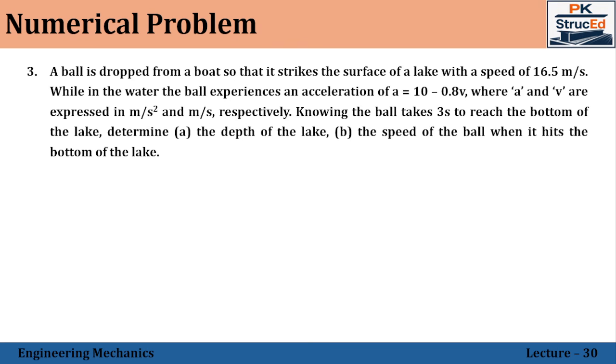First of all, you can see the relationship is given for acceleration in terms of velocity. A ball is dropped from the boat so that it strikes the surface of the lake with a speed of 16.5 meter per second. While in water, the ball experiences an acceleration. It's not moving along with gravity because it is inside the water. Knowing the ball takes 3 seconds to reach the bottom, we are supposed to calculate the depth as well as the speed when it hits the bottom of the lake.